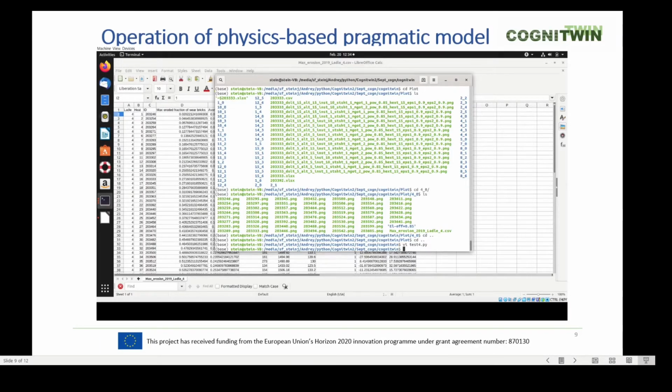So typically we would like to use methods like fractional designs and factorial designs for doing this. But to do that, we need to have a very good idea about where we should have our center point. So this is a sort of iterative process. But at the end, we can run all the cases and see if we can find a set of tuning parameters that can be used for all the cases.